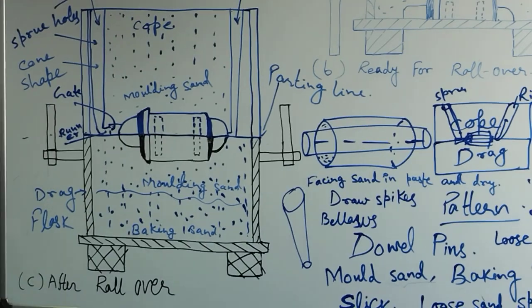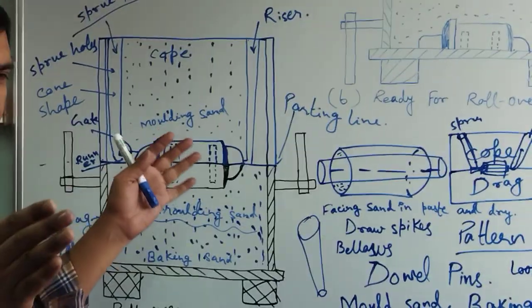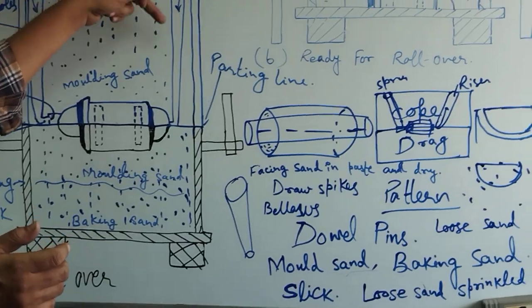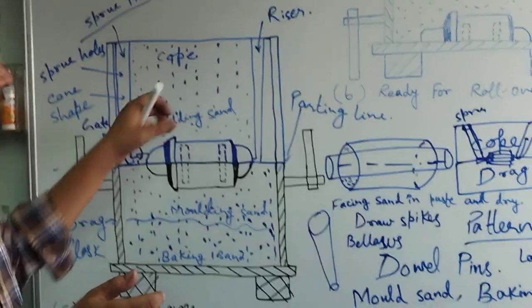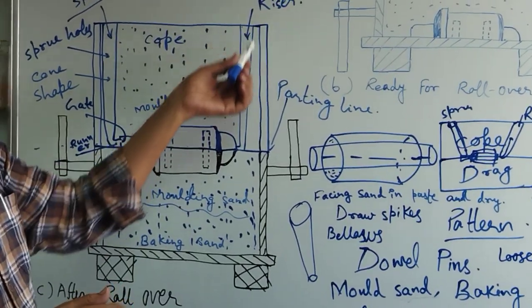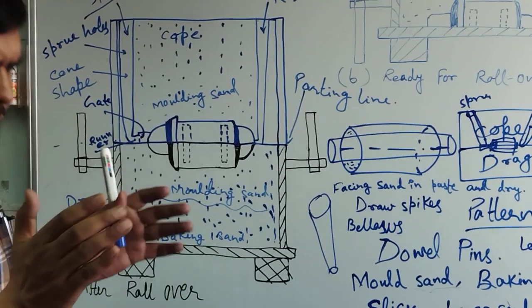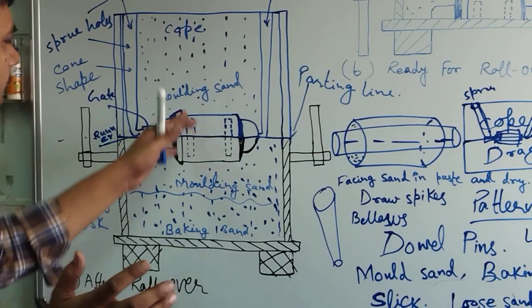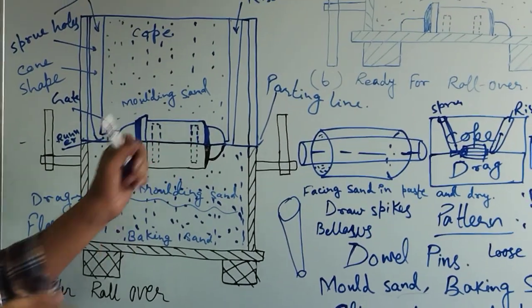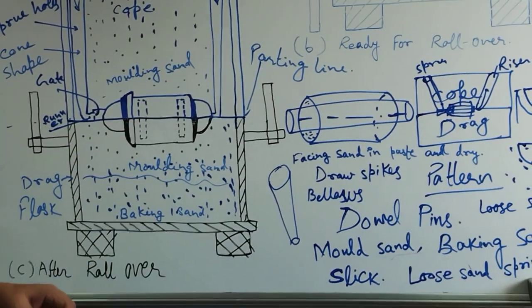During solidification the metal shrinks, so excess metal is required to make up the overall volume of the object. The riser metal comes down and overcomes the volumetric contraction of the object, making the full volume of the object after solidification.